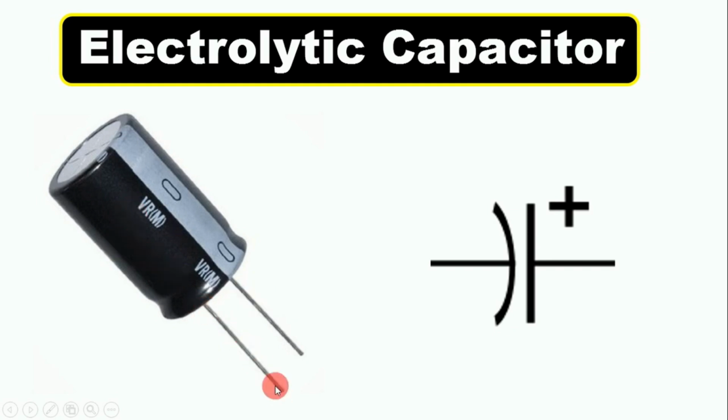In this capacitor, the bigger leg will be positive, and the shorter leg will be the negative terminal. If in this capacitor both the legs are equal, then in this condition you have to observe this strip. This gray strip you can see here has a negative sign on it. This means that this leg here is negative and the other one is positive.